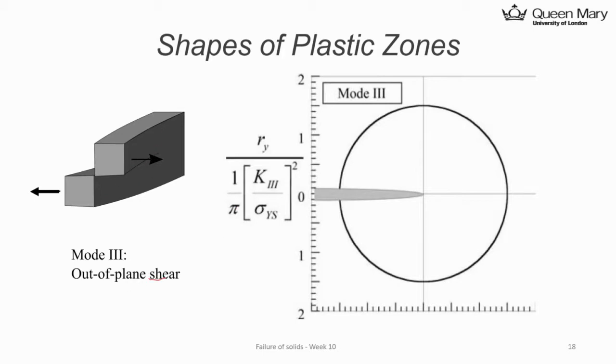So it's the out of plane shear. In that case, plane stress and plane strain are the same because all the stress is out of plane. So essentially you will get identical solutions for plane stress and plane strain.